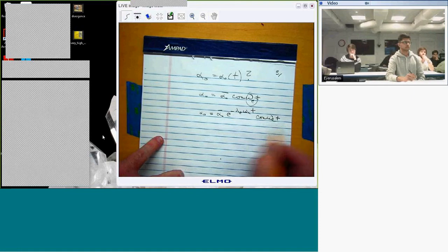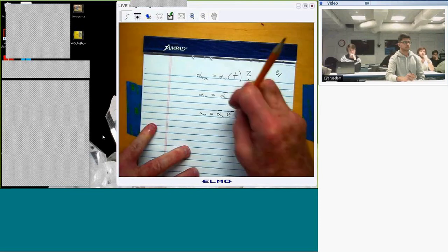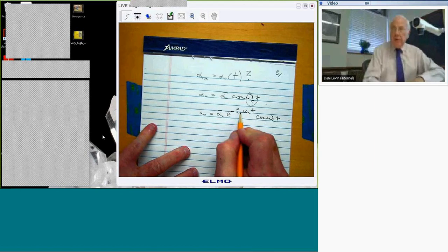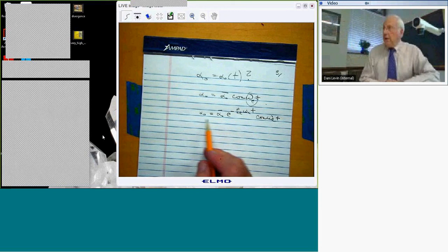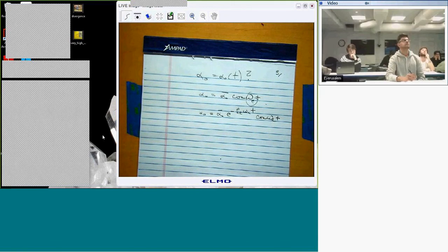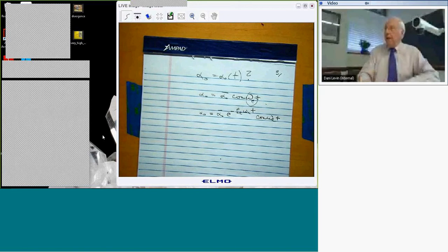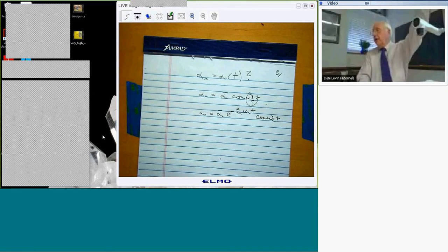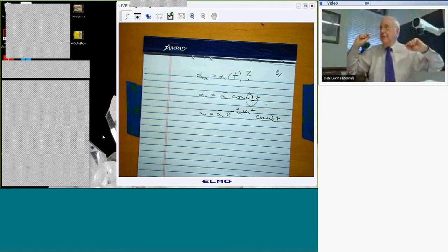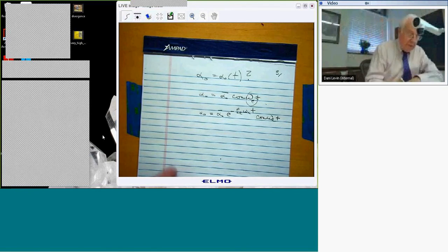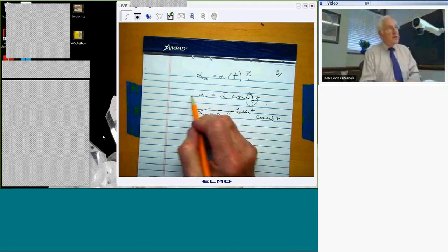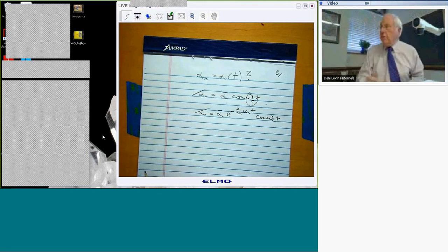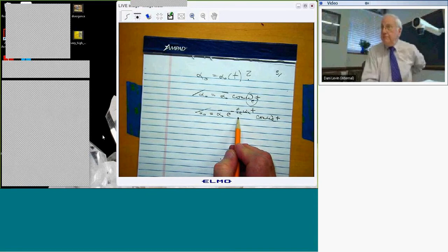Apparently it's not a lambda; I think it's probably zeta, because it's a decay, but a decay associated with the external excitation. So what happens with this alpha naught at large time? It goes to 0. So at a very large time, I can forget about alpha naught, and I'm back to the case where alpha naught is 0. If I really want to know what's happening at large time, in some ways this case is actually easier than this case, because here the excitation persists forever. Now this is actually the special case when zeta E is 0.